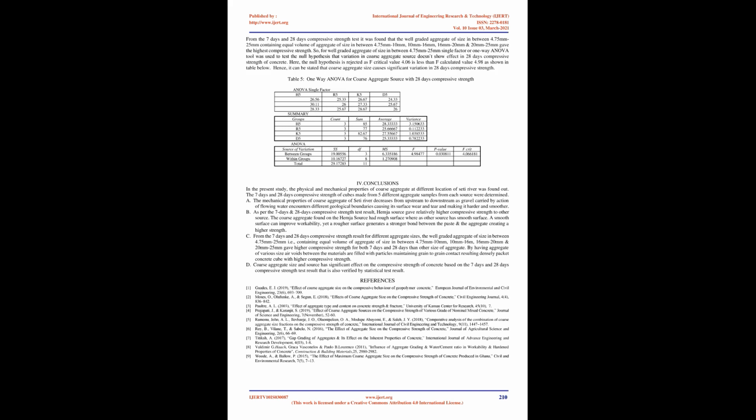strength. Conclusions. In the present study, the physical and mechanical properties of coarse aggregate at different locations of Seti River were found out. The 7 days and 28 days compressive strength of cubes made from 5 different aggregate samples from each source were determined. The mechanical properties of coarse aggregate of Seti River decrease from upstream to downstream, as gravel carried by the action of flowing water encounters different geological boundaries, causing surface wear and tear and making it harder